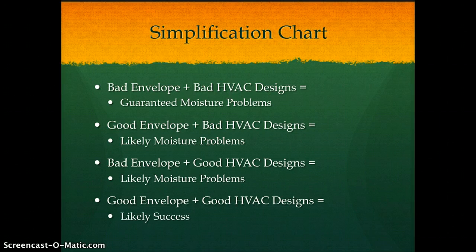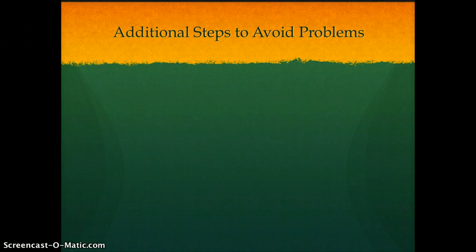Although new wall system products are often intended to provide better thermal insulation, reduce air movement through the walls, or allow enhanced drying of the wall assembly via vapor diffusion, they can also perform in unanticipated ways. These new products can dramatically change the way moisture flows through the wall and roof systems and the potential for condensation within these cavities. The use of these new products mandates that the designer implement several additional steps to